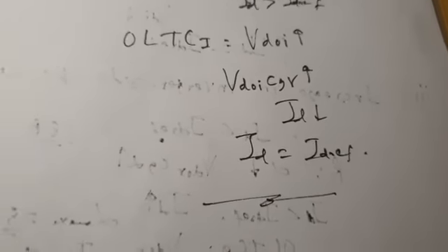So this is how your controller operates for various problems. If rectifier side input voltage increases, if rectifier side input voltage decreases, or if inverter side input voltage increases or inverter side input voltage decreases, then this is how the controller operates. The controller takes very quick action. First, electronic action, alpha control. If alpha control fails, then online tap changing control, and it always maintains ID equal to IDREF, constant DC line current.